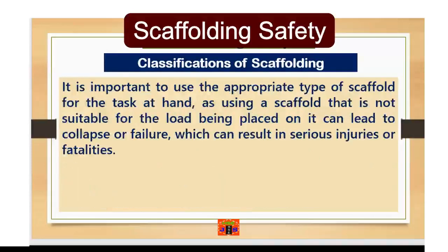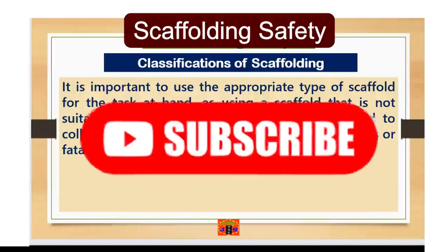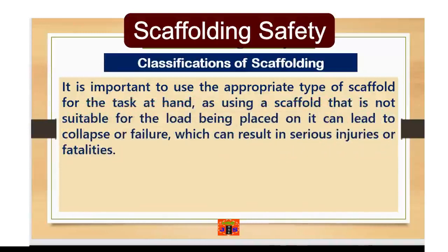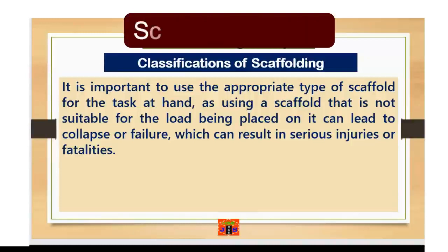Remember, it is important to use the appropriate type of scaffold for the task at hand, as using a scaffold that is not suitable for the load being placed on it can lead to collapse or failure, which can result in serious injuries or fatalities. What it means is, you will not use a light duty scaffold to complete tasks which require a heavy duty scaffold.